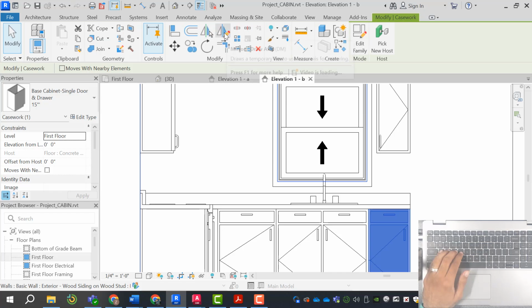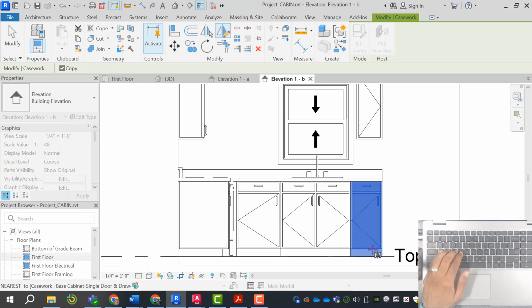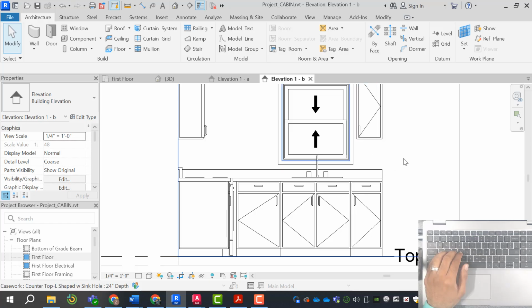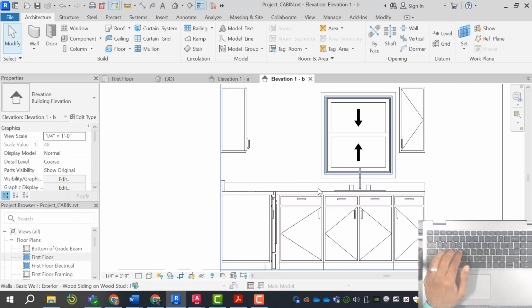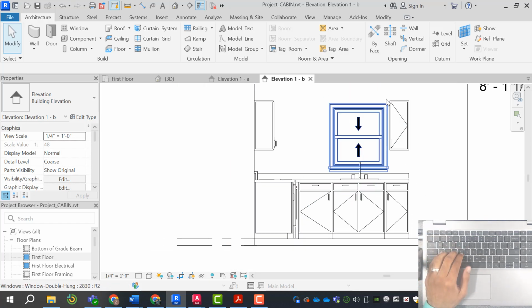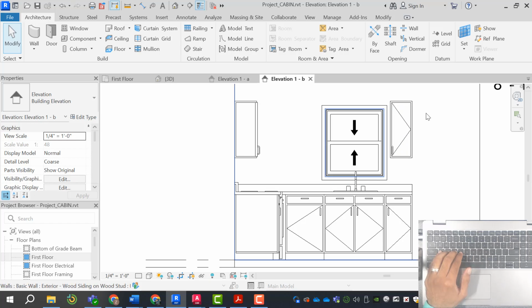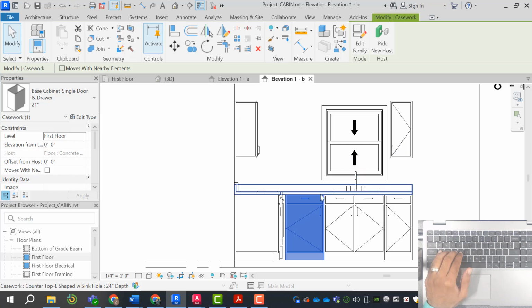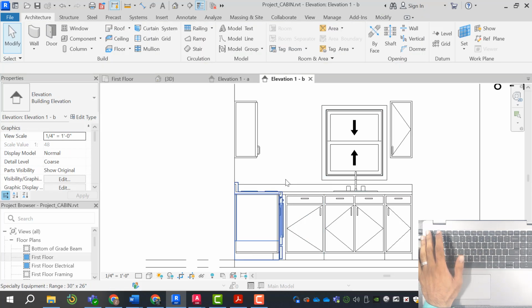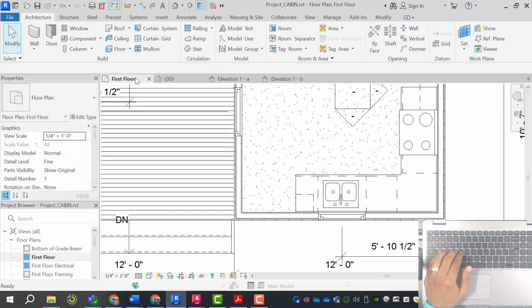Now, I'm particularly peculiar about my details, but it's really up to you how you're going to detail it. Now from here, let's go ahead and bring some upper cabinets across. Just like we shrunk 3 inches on this side, because this is 21, we can do an 18-inch upper cabinet and then align it to this edge. Go to first floor.